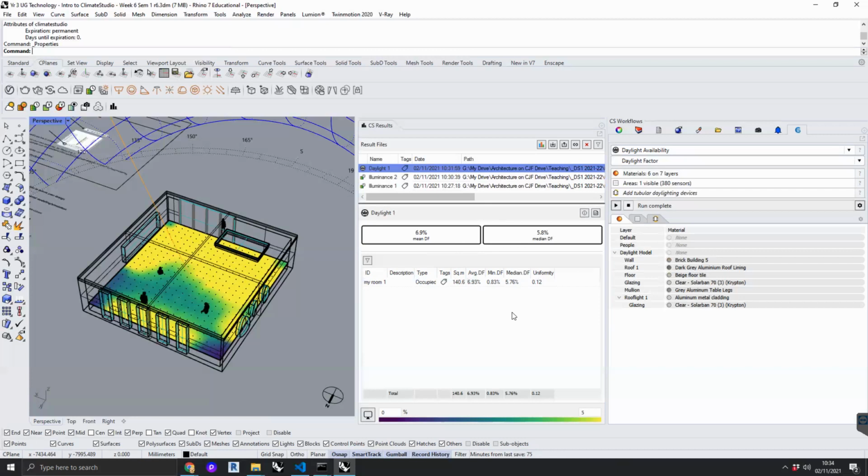But you might have some trouble with just having too much light. Like right now, this sunlight is in my face and it's kind of annoying. So maybe I praise myself for having a high daylight factor, but I also have sun in my face for half the year and it's annoying. So you've got to weigh these things up, like what daylight factor is going to feel good for what you want to be doing in your building.